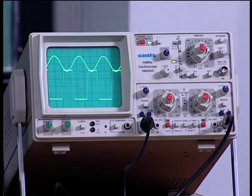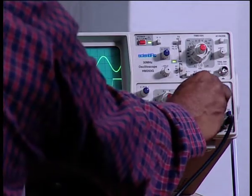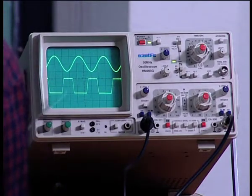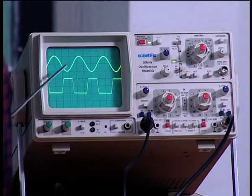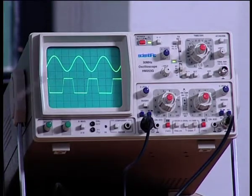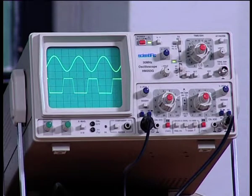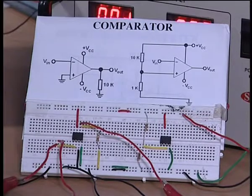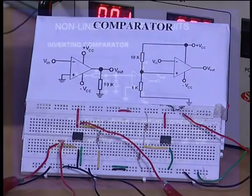Now you see this is better, now you are able to see the thing. So you can see the voltage is now in 10 position. So it is about 20, the amplitude is 20, plus or minus 11 or 10, and therefore it is about 20 volts peak to peak. So this is again another example of how a comparator can be used for getting a sine wave converted into square wave.